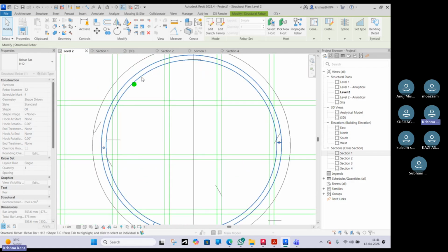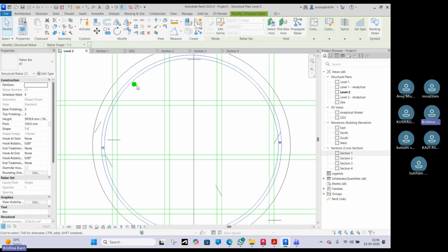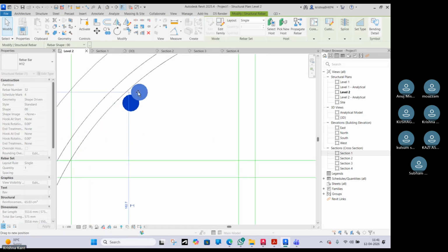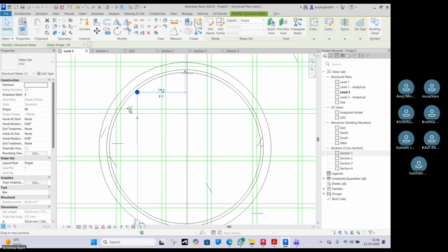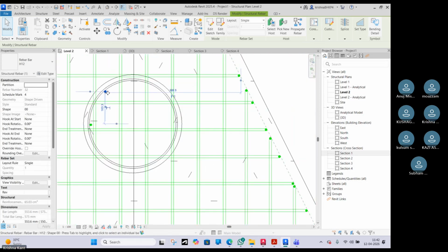Now, stirrups are generally not provided with 12 mm diameter. There will be 8, certain times 10; 8 is also fine. So stirrups are very thin, but the main bar will have more diameter: 12, 15, 16, 20, okay? Like that, the main bar will be there. I'm copying it based on how many numbers are provided.